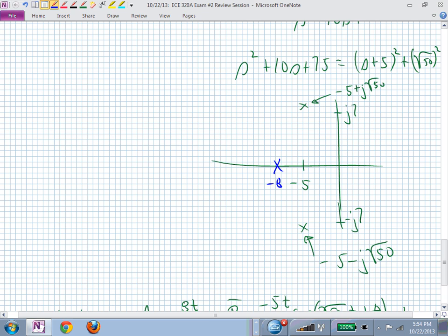If you do the quadratic formula and you end up with complex roots with positive real parts in just a pure RLC circuit, I would say I must have an algebra mistake because I have roots in the right half plane, and an RLC circuit should decay with time. It should have some damping. That's what the resistors do. Is that okay? Did that answer your question?